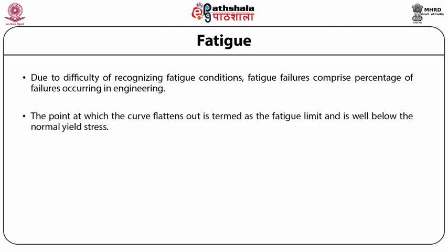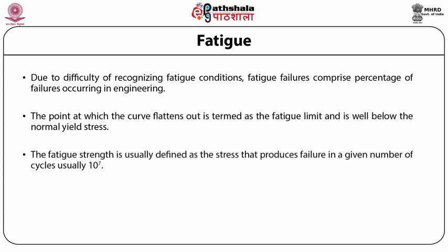The point at which the curve flattens out is termed the fatigue limit and is well below the normal yield stress. The fatigue strength is usually defined as the stress that produces failure in a given number of cycles, usually 10 to the power 7.